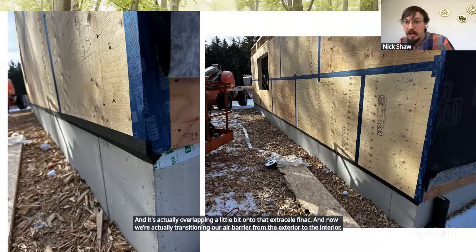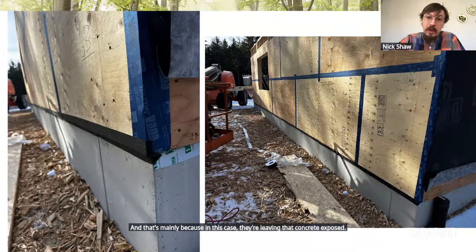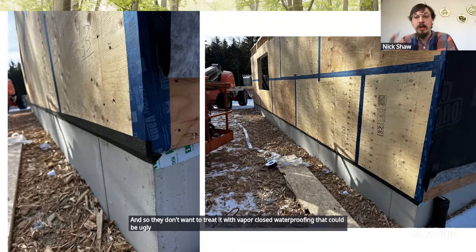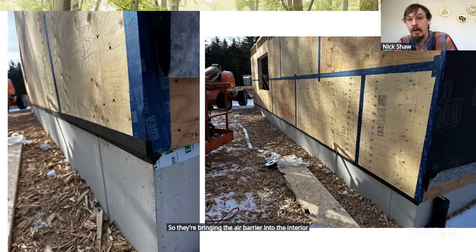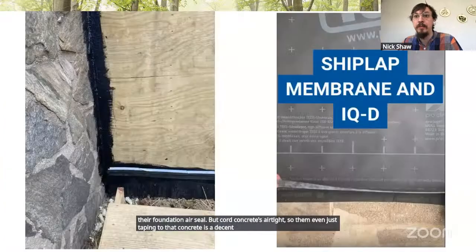And that's mainly because in this case, they're leaving that concrete exposed. And so they don't want to treat it with vapor closed waterproofing that could be ugly, and then they would have to conceal that. So they're bringing the air barrier into the interior side of the assembly for their foundation air sealing. But poured concrete's airtight, so them even just taping to that concrete is a decent airtight connection.